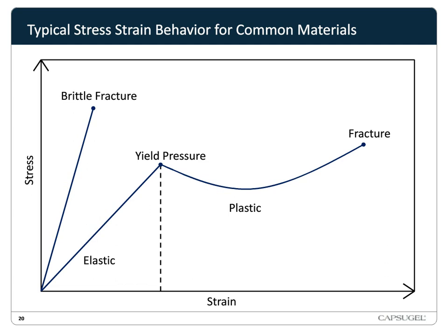and the material deforms. The yield strength is the force necessary to initiate this deformation. Contrary to plastic deformation, we have brittle materials, which instead of yielding and plastically flowing, fracture at their yield pressure, and this exposes new surface area.